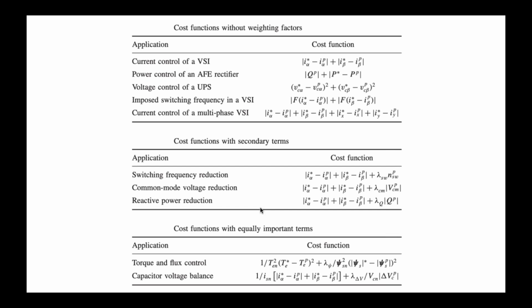In the cost function, they calculate the error. Particularly in electrical drives, they calculate the torque error as well as the flux error, because torque and flux are the control variables. By using a single cost function, we are able to control the machine. Why unnecessarily take another controller like fuzzy logic? No need, it is not required for this application. Right? Fine.